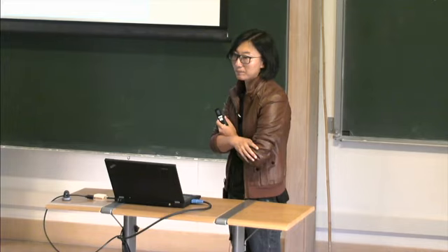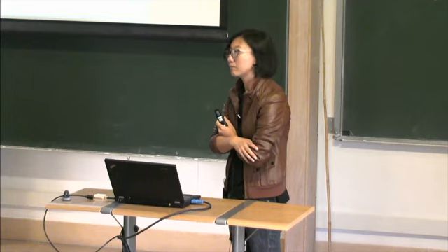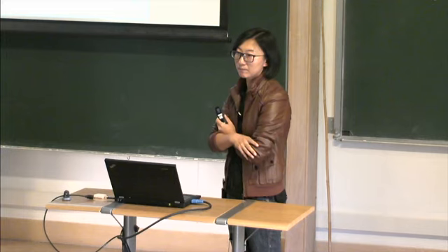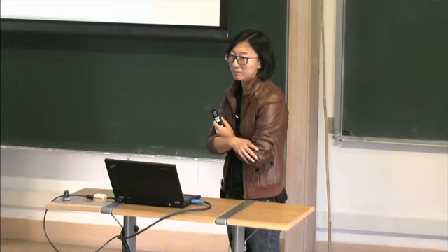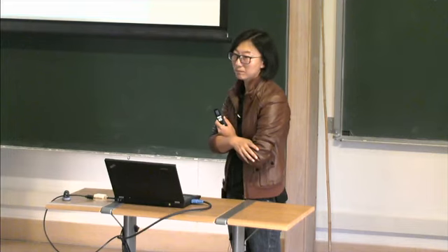So in fact, these are the results you'd expect. You'd expect that the maximum drag would skew, and as you increase the fractional blockage by the object, you'd expect it to move downwards, further away from Froude number 1. The maximum occurs at less than Froude number 1.